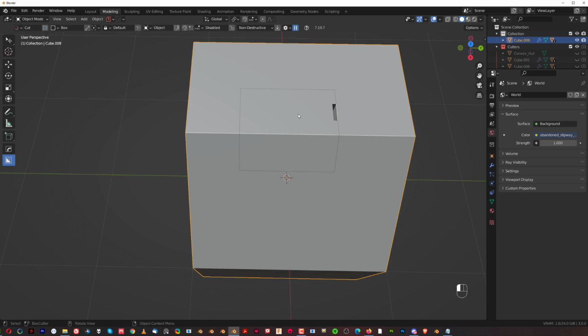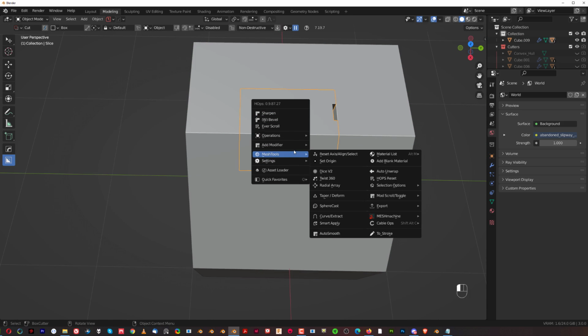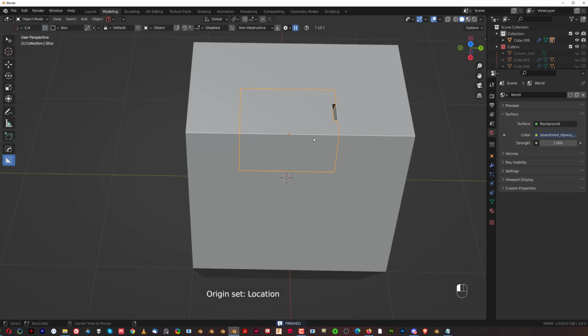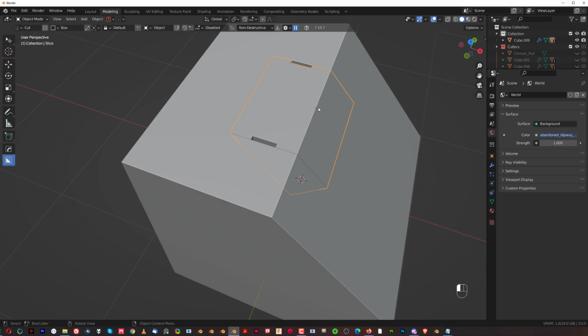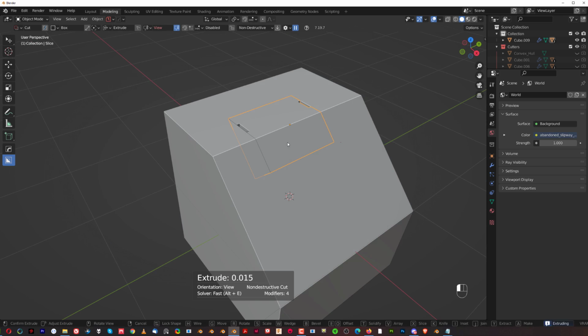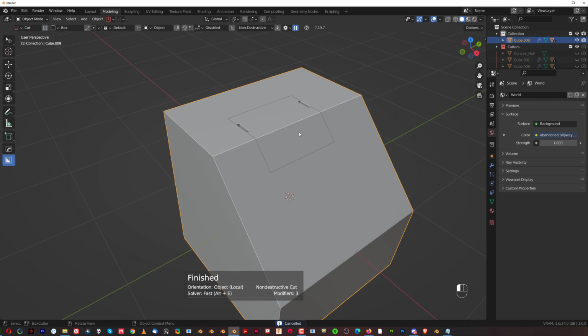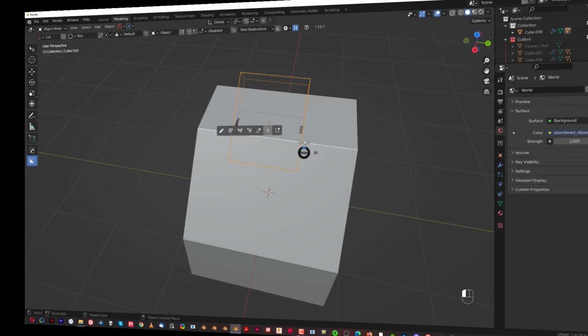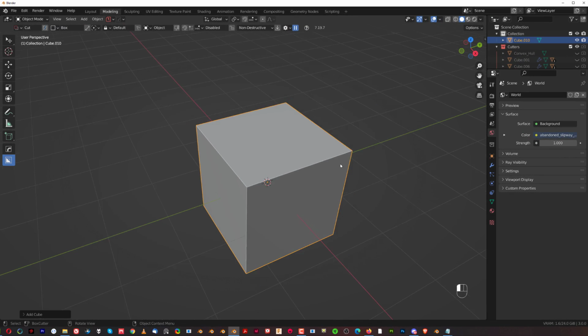But if I click that cutter and go to mesh tools and set origin, I can actually set origin on that cutter, and now I can mirror the cutter across the origin of this cut, which technically doesn't exist because, you know, it's a live cut. So the coolest thing is I can move it, and it's going to move with that origin point. That's pretty badass.